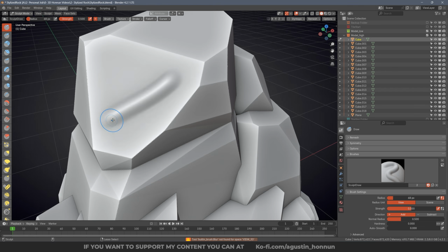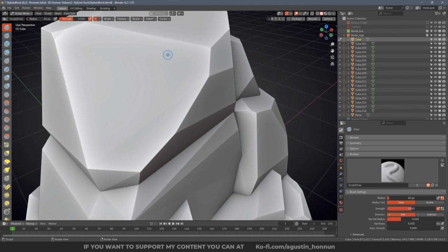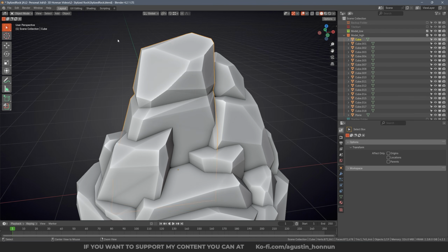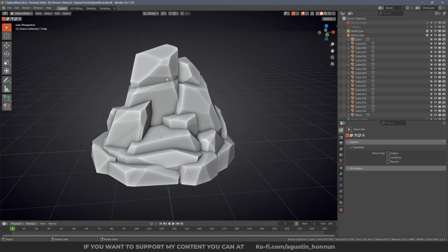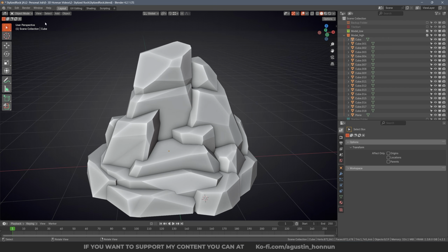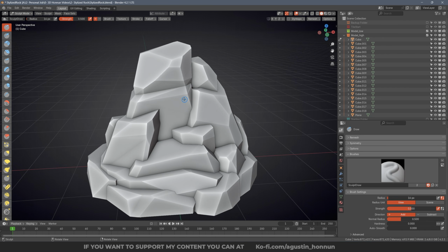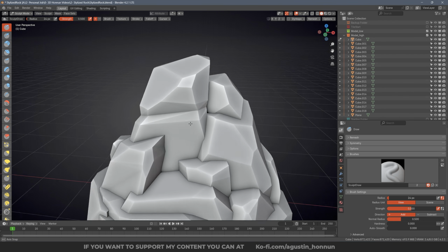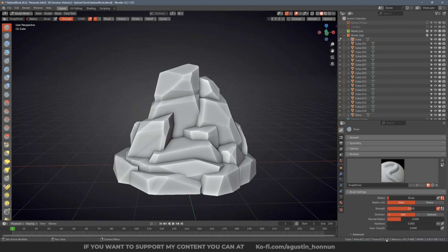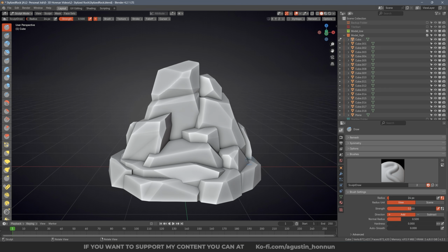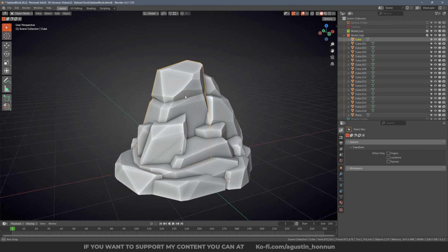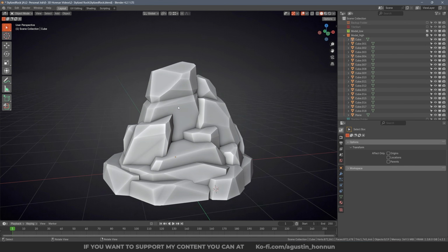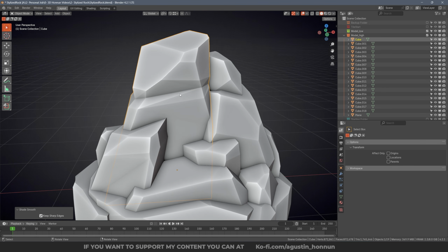Let me check. Yeah, we can add some fine details even with that resolution. If your PC can handle that amount of triangles, you can go with this one or even lower values for more quality. Blender nowadays is very optimized for sculpting, so you can go to really high values and sculpt very well that way. I've sculpted models with more than 50 million polygons, so again, if your PC can handle that, go with that value. Okay, I'll be using 0.4 remesh value.